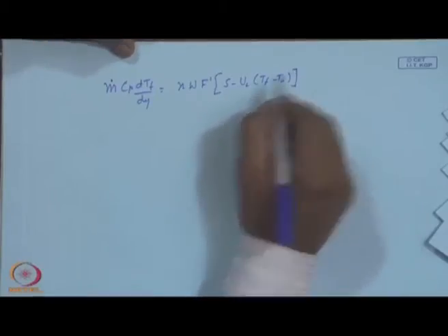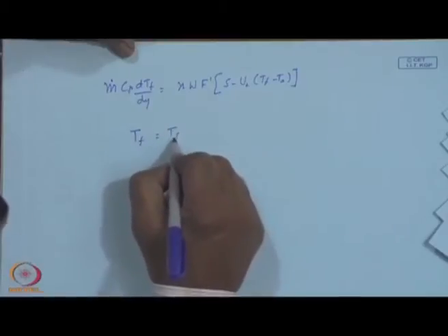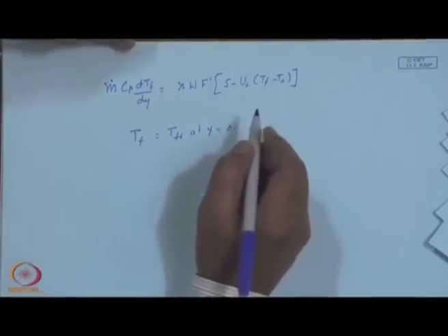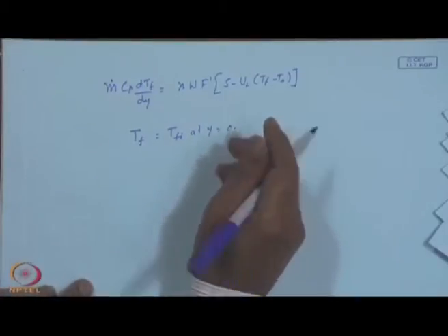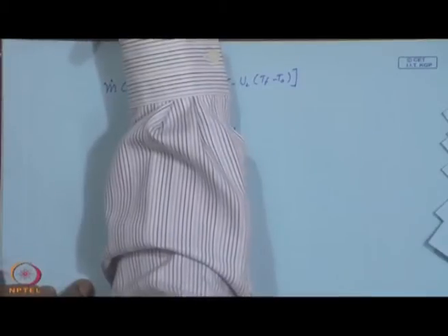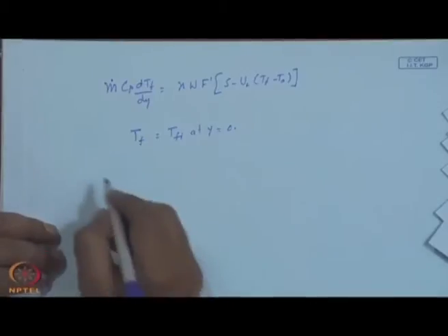the one boundary condition that you will be requiring will be T f equal to T f initial at y equal to 0. The temperature at which the fluid enters is the boundary condition needed here. So, it is simple to integrate, it is a first order equation only.